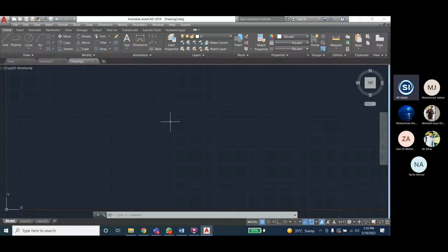If this window is filled, there are multiple options. For example, just select this one like this and then move. In Modify, you can move it. For example, move. It is saying specify base point. From here, you want to move. You want to move from here, for example. Now OSNAP is not on. OSNAP always on. Okay.